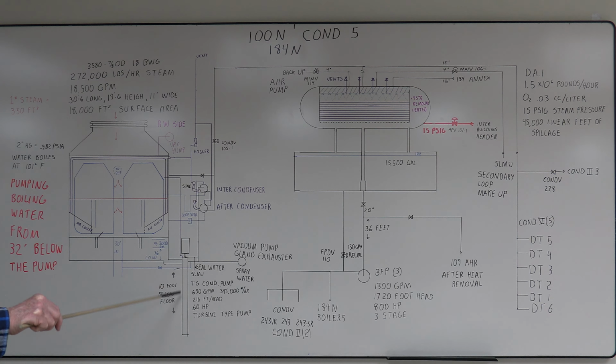So this is actually seeing the same pressures inside here. It doesn't care about atmospheric pressure. And then the 10 foot down, it helps build a little bit of net positive suction head and raises the boiling point of the water. So after you went through the first stage pump impeller, you'd be back up above atmospheric, you'd be fine.